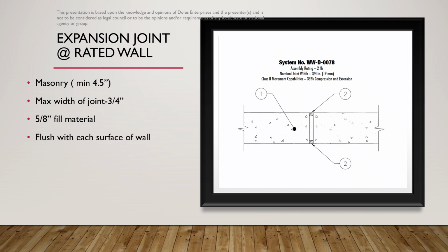However, the inspection process becomes a little more tricky at that point. Again, during the inspection process, you'll have options. You can witness the actual installation for a certain percentage, or you can do some destructive testing. Either one is at the option of the inspector and the process for construction. Again, use the UL assembly, read it specifically, and make sure applications in the field match the UL system design sheets provided.